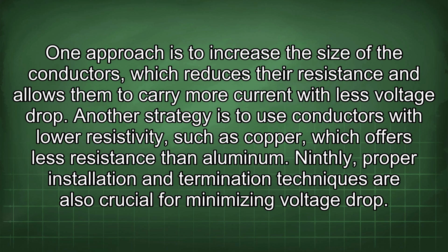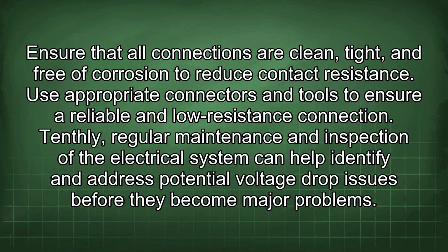Ninthly, proper installation and termination techniques are also crucial for minimizing voltage drop. Ensure that all connections are clean, tight, and free of corrosion to reduce contact resistance.